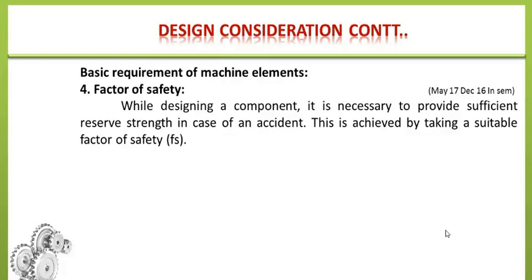Now you have to select a particular material for that design component. That material has some ultimate tensile strength and yield strength, so these specifications are present along with the material. The component performs a safe operation when the stresses produced on it are less than the strength of the material. Then and only then can you say that the component performs well during actual working condition.